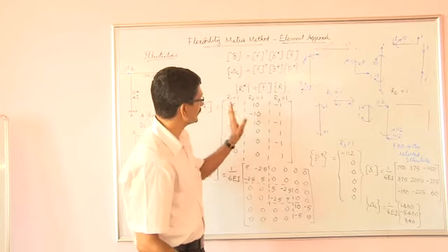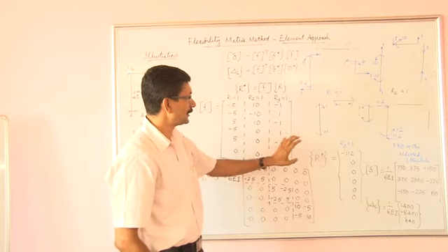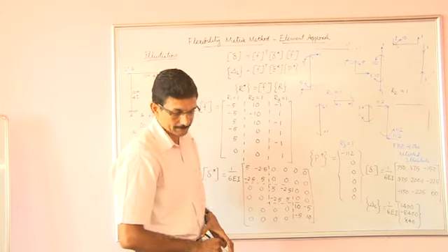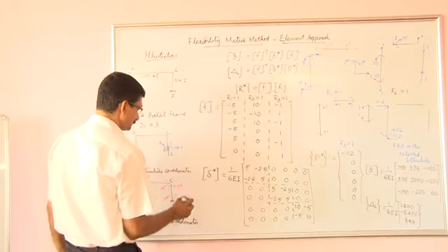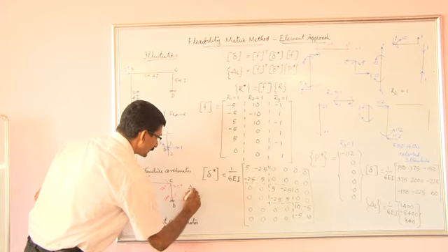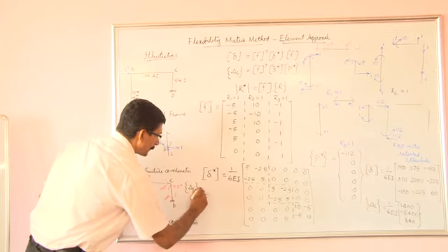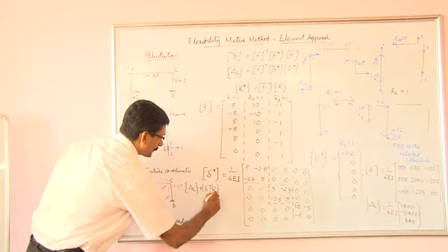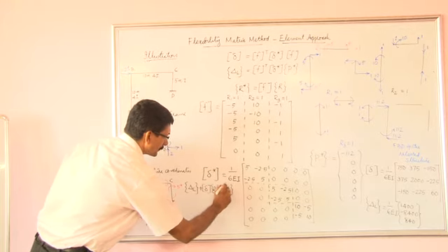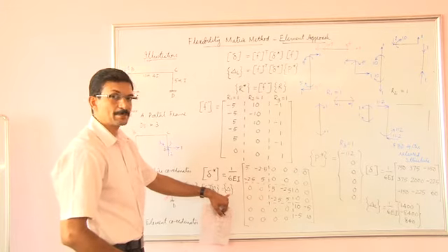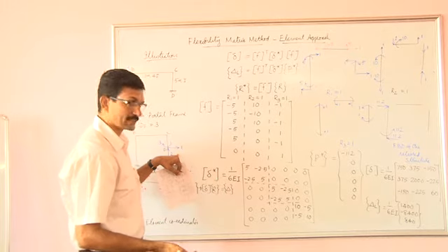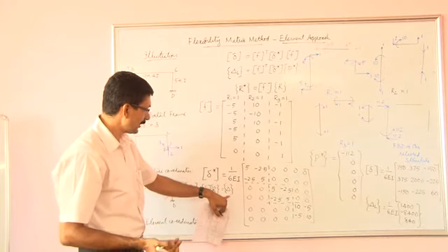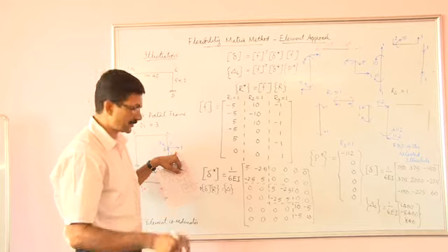The only advantage of this case is that we have a systematic approach in developing the flexibility matrix and the delta L vector. And for completeness, the solution is given by solving the equation delta L plus delta matrix into R vector is equal to delta. Well, delta is the displacement corresponding to structure coordinates. Applied displacements correspond to structure coordinates, and they are zeros. They in fact account for the support settlements and support rotations. They are zeros over here.